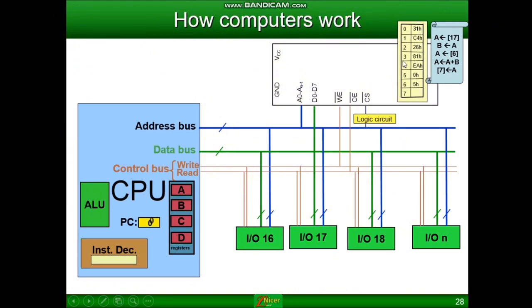So now moving on. First of all, the program counter gives out 0 as it needs to access the data line wise separately. In 0 we have 31H as the information. This 31 is going to go to the instruction decoder.